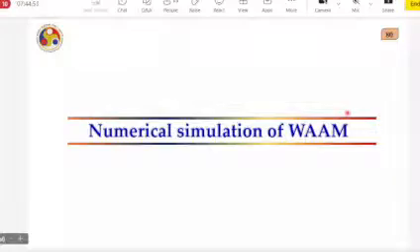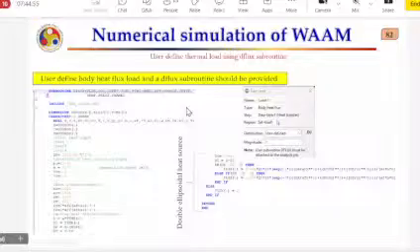For meshing also, you define the mesh there, like mostly the triangular mesh. It's commonly used, and it's quite simple also. But if your solution is not converging at a faster rate, then you may go with some other meshing option as well, maybe some hexahedral mesh or quadrilateral mesh. So these things we can just check by running the simulation early.